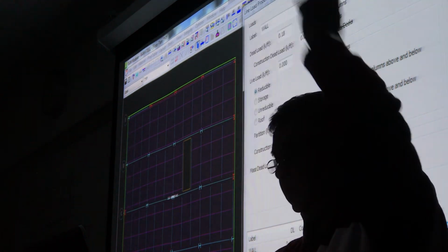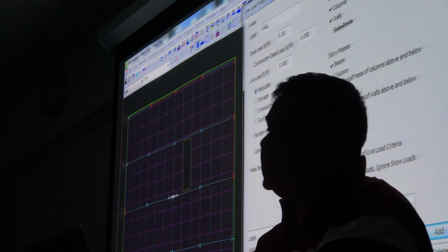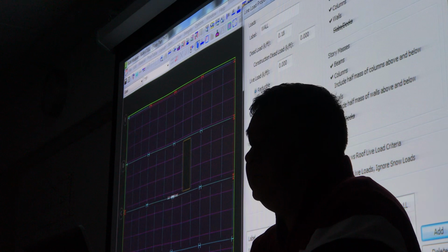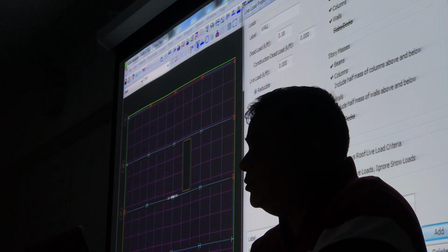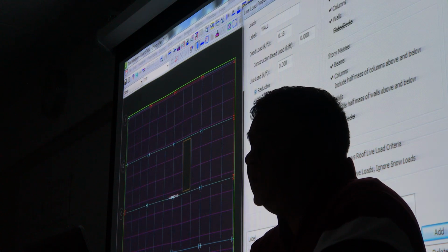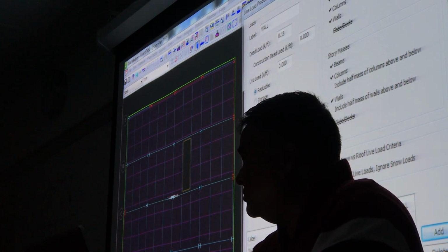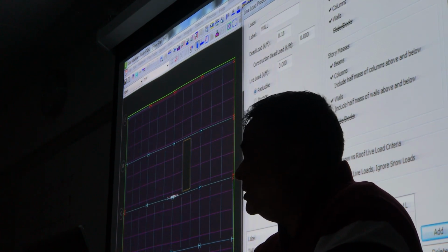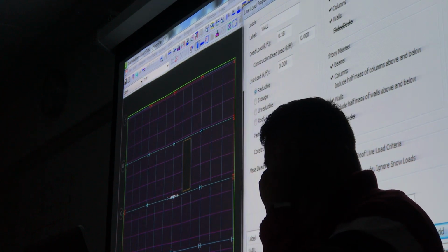Okay. Now, why do we need that wall? Also, if it is a glass wall, remember that glass walls cannot deflect a lot. That means the beams below the glass need to be designed for very small deflection. The amount of deflection allowed is 0.5 inch. So that's why you need to know where your wall is and how much load it is going to give to the beam. The beam cannot deflect more than 0.5 inch. Okay, I'm going to say okay.